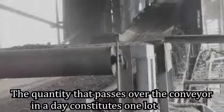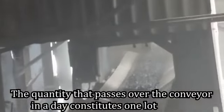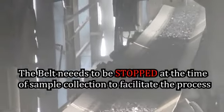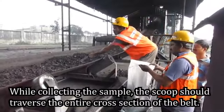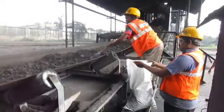The quantity that passes over the conveyor in a day constitutes one lot, which needs to be divided into a number of sublots for the purpose of sampling. For example, if the quantity to be passed in a day over the conveyor is 600 tons, then there will be 3 sublots of 200 tons each. While collecting the sample, the scoop should traverse the entire cross-section of the conveyor belt.